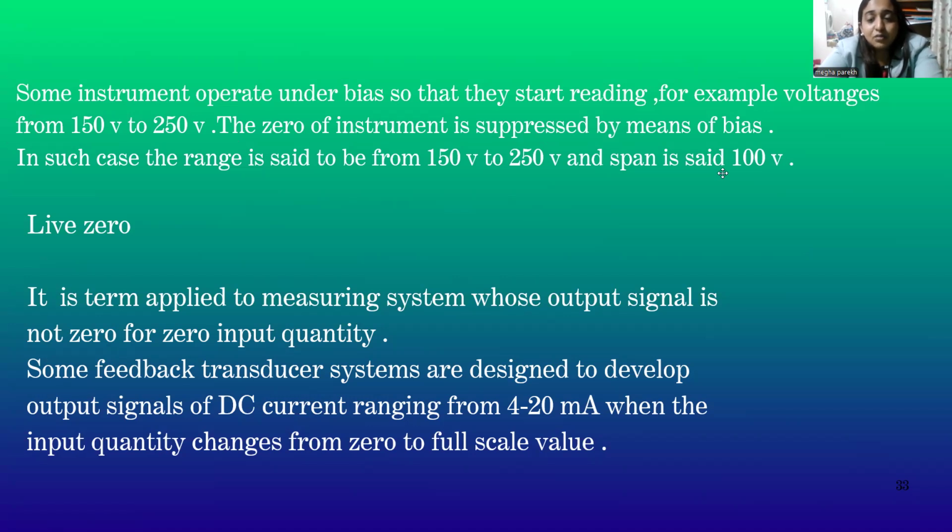Live zero is an important definition because in some instruments, we set 4 to 20 milliampere as the zero for the practical readings of the instrument.